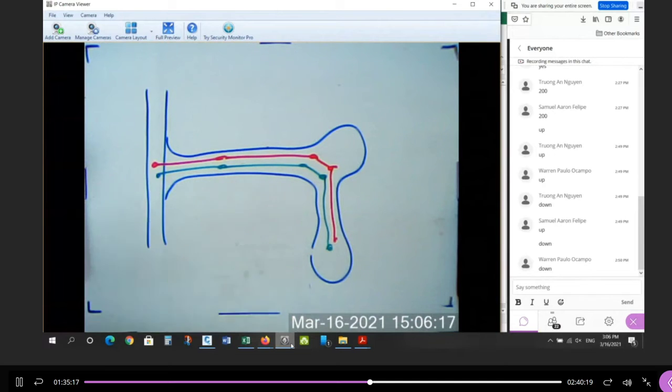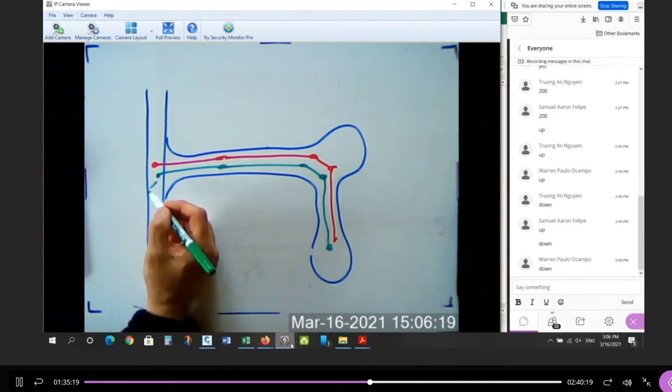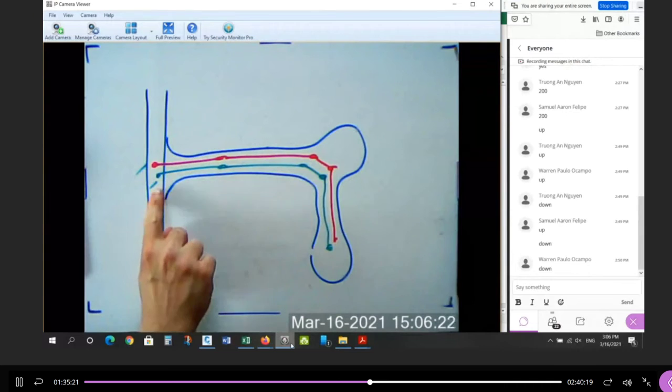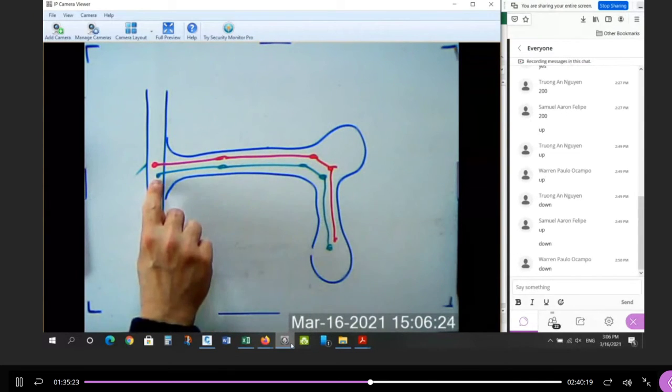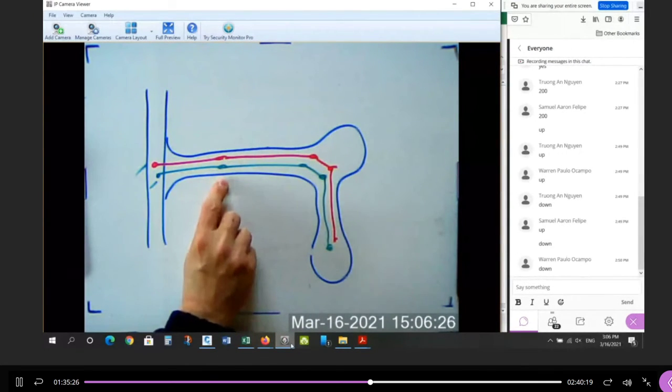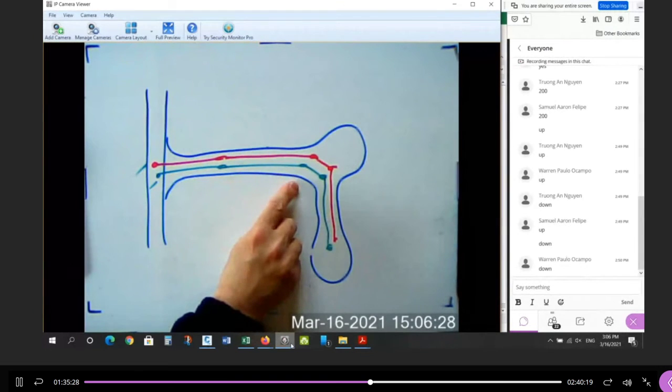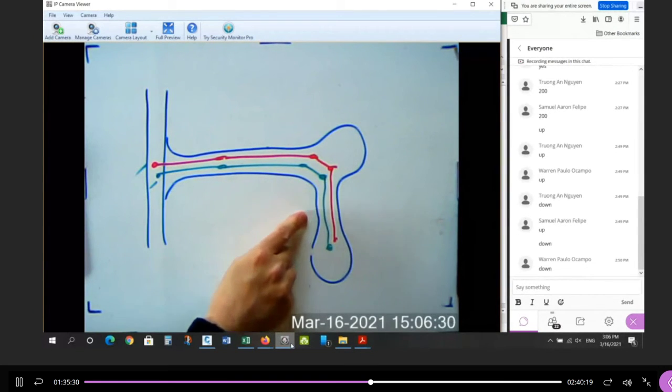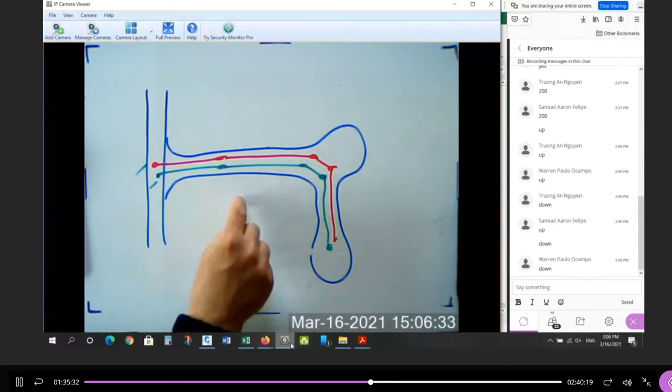The design then started with these inverts. I know the invert here, I know the invert here, and then I went upstream, right? So I went distance slope, add the minimum drop, distance slope, add the minimum drop, distance slope, add the minimum drop, distance slope, get the invert. So that's how we calculated this.